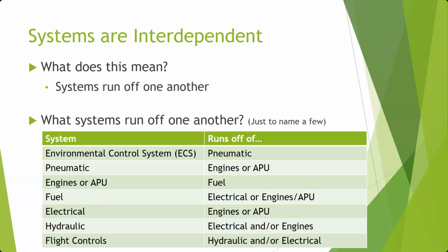So as you're looking at these different systems, as we're learning about them, keep that in mind. The flip side to that, from the safety aspect, is if I'm going to turn something on, what is that going to operate? Right? We brought up hydraulics. You mentioned landing gear. If the plane's on jacks, you flip on hydraulics. What do you think happens if someone left the gear handle in the up position and the gear are down? As soon as you turn on hydraulics, what's going to happen? Gear's going to come up.